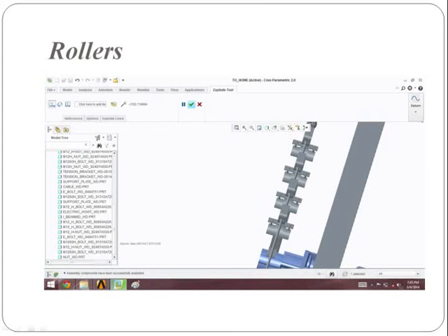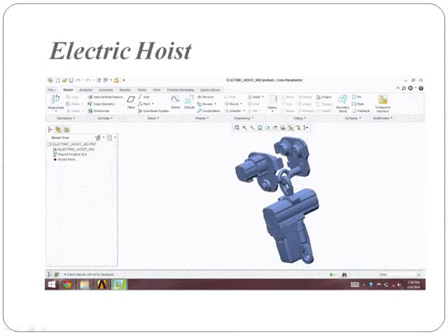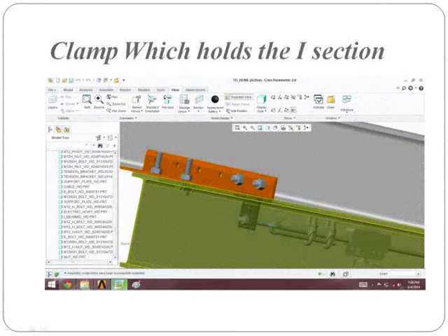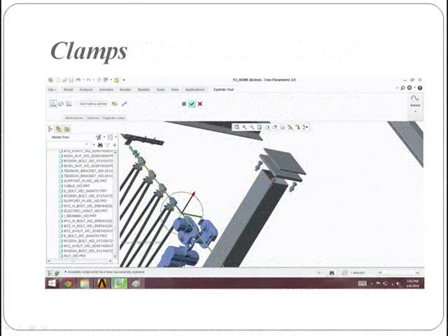Types of beam sections: standard section shapes, W wide flange, S American standard beam, C American standard channel, L angle, WT or structural T, pipe, structural tubing. I section: the cross-section is symmetrical to both axes and constant in the whole span of the beam. The web is not subjected to transverse loading causing crushing, crippling or buckling failure. The possibility of shear buckling is excluded. The beam is not subjected to axial force.